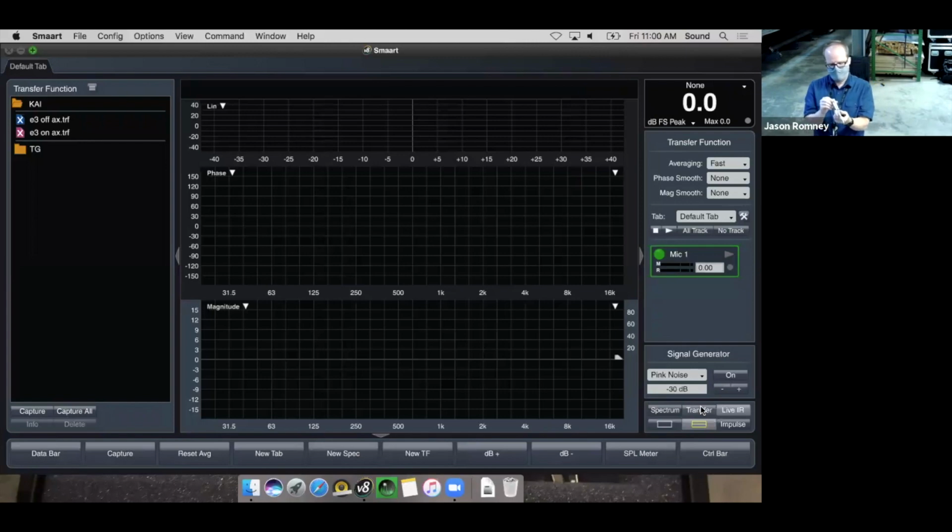But what you want in an analysis microphone is a relatively flat frequency response, as flat as you can. Not all microphones have a flat frequency response, and that's not bad, right? An SM58, for example, does not have a flat frequency response, and yet it's one of the most popular mics out there. Why? Because its natural frequency response sounds good for a lot of things people like to use it for. But it is a very not flat microphone.